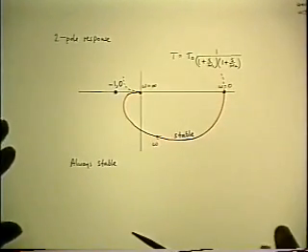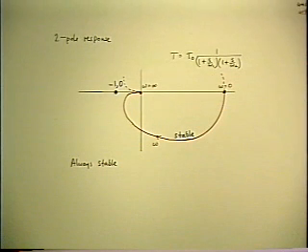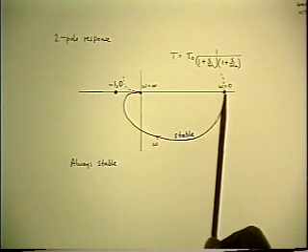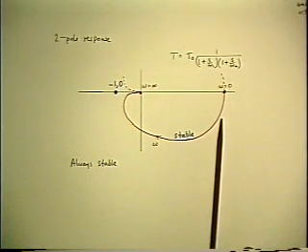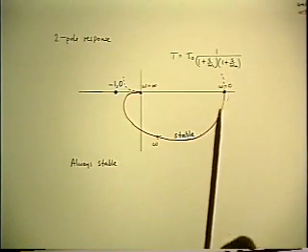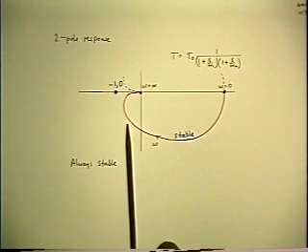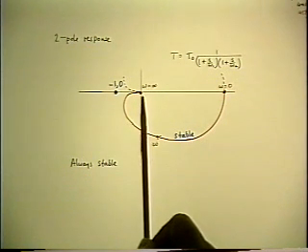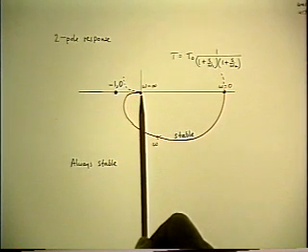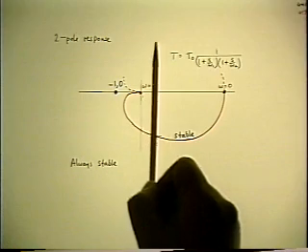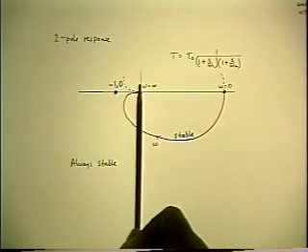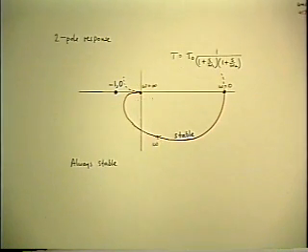So that's the base comparison position. The next most interesting case is two poles. You start out at zero frequency the same way on a semicircle, but then as you get close to the second pole, the magnitude will go down faster and the phase angle will increase faster, and you'll eventually go to an infinite frequency at zero magnitude with a phase angle of 180 degrees. And then you have the vertical inversion of that also that closes the contour, and you look at it and you say, does it go around -1? And the answer again is, no it doesn't, and it never will.